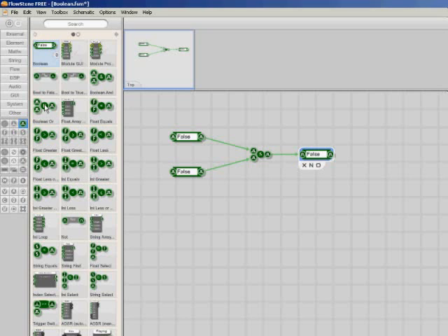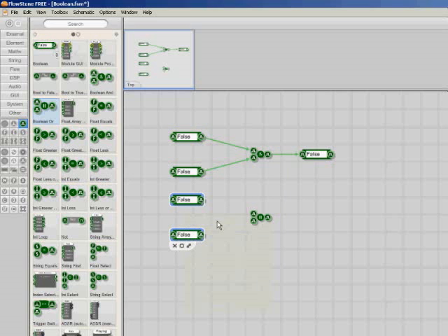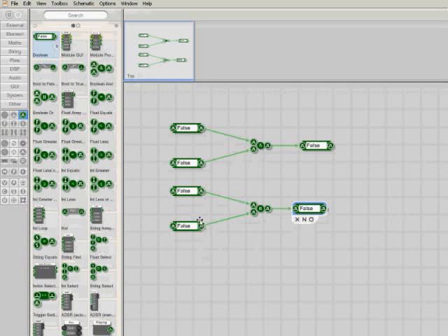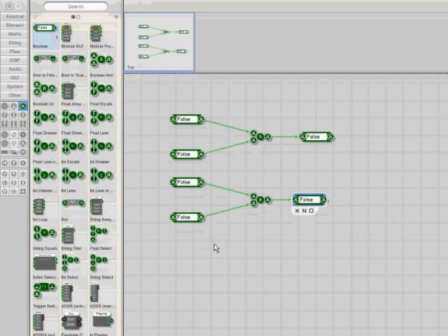Okay. So now I'm going to do a Boolean OR, drag the little OR function in, and what I can do is copy these two elements by right-clicking, choosing copy, then right-clicking, choosing paste. Saves me a little time, and I can wire those into the inputs of my OR gate. I can also drag in another one for the output, and here we now have our OR gate wired in. Two false inputs gives us a false output. Any one is true, because it's an OR, gives us a true output. 1 OR 1 equals 1.